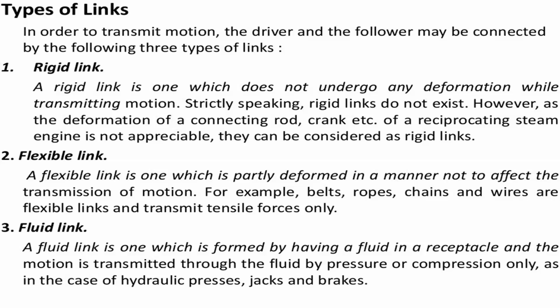Next, the third one is the fluid link. A fluid link is one which is formed by having a fluid in a receptacle, and the motion is transmitted through the fluid by pressure or compression only. Generally, these fluid links do not exist in kinematics, so we do not create any loop to find this fluid link here.